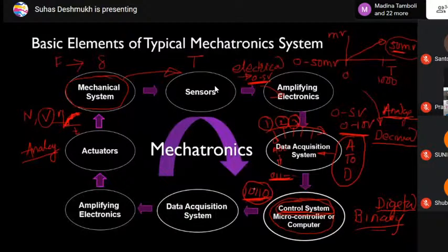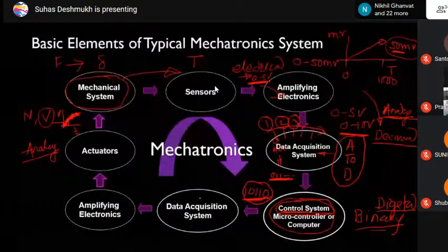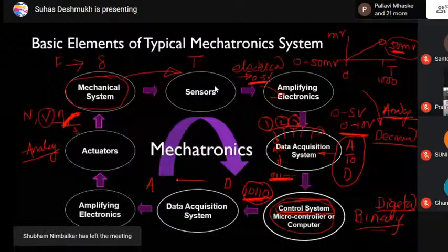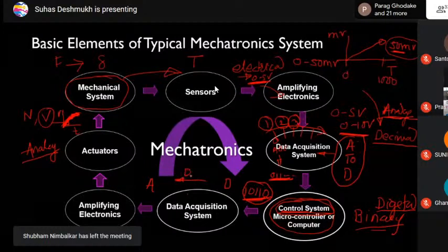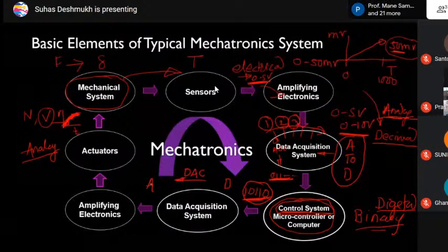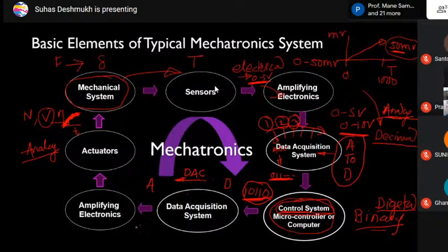Analog. That's what this here comes upon. Here it is a digital number. Here it is an analog number. That is to be converted. Then it is the reverse of ADC. It is called a DAC, digital to analog converter. The digital to analog converter will now generate a signal that is 0 to 5 volt, maybe 0 to 10 volt, sometimes minus 10 to 10 volt, like this. So it depends on the configuration of your microcontroller.